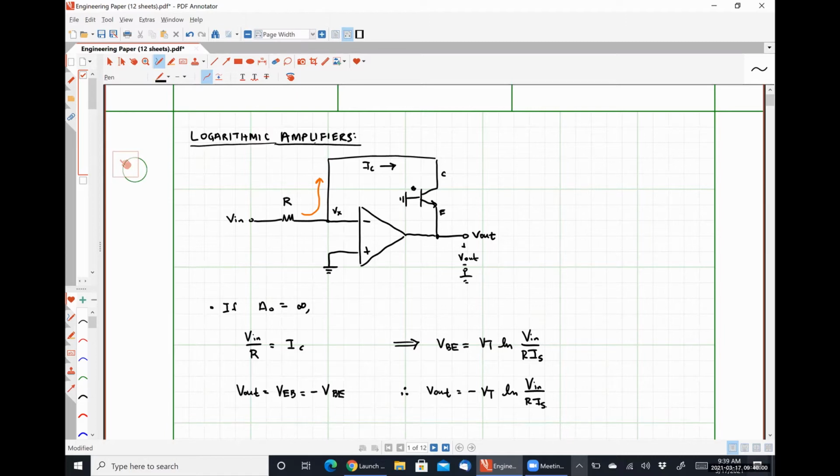So let's talk about what that odd behavior is real quick. What happens if Vn is less than 0? That transistor turns off, right? It cannot conduct current, so it looks like an open circuit. So if the feedback loop is thrown away, we now have an open loop circuit. Do you guys remember how open loop circuits behave from back in circuits 2 when you had me a couple of years ago?